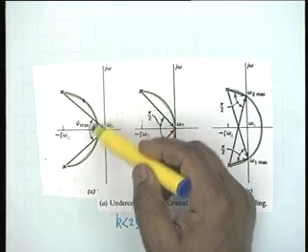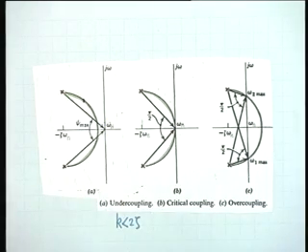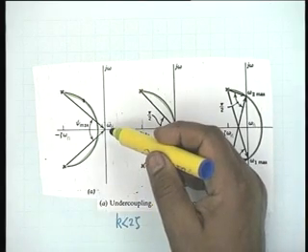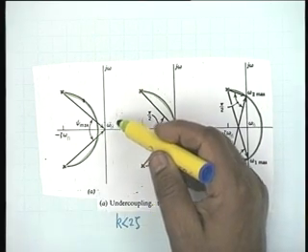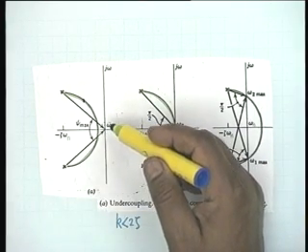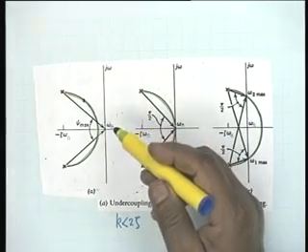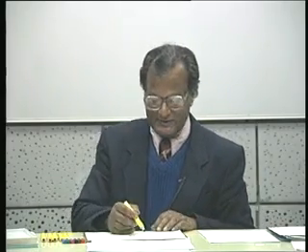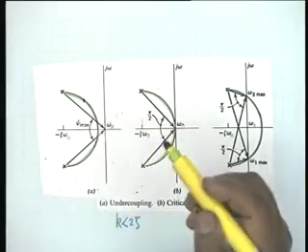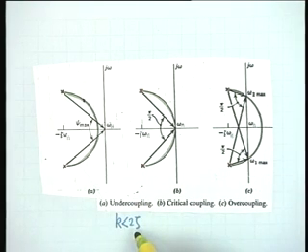As you go this way, the angle goes on decreasing. And therefore the maximum, as is justified by common sense, when k equal to 0, obviously the maximum shall occur at the natural resonance frequency of the tuned circuit, that is at omega n. So the maximum still occurs at omega n as long as k is less than 2 zeta.